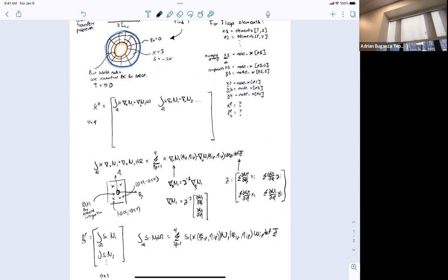And you need those values of the nodes because then you use these values to get the x and y coordinates. Right? Maybe the file is not uploaded. I was just messing around with the CD, trying to understand. But that one you don't need to worry about. It's just going to read the mesh, and all it does is create these two arrays. One array has all the XY points, and one array has for every element, what are the four nodes that make up that element. That's basically what it's done.